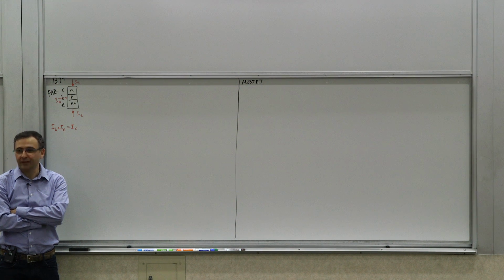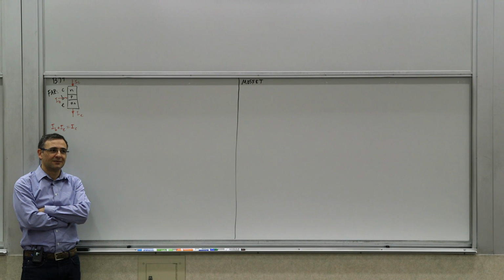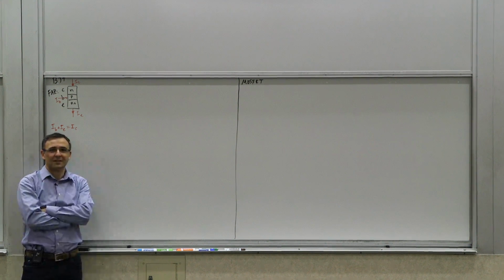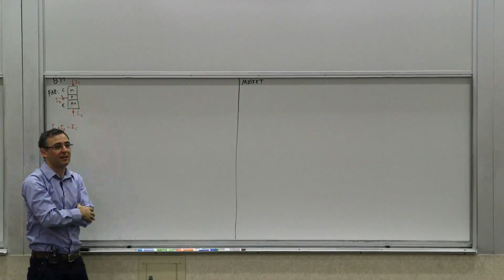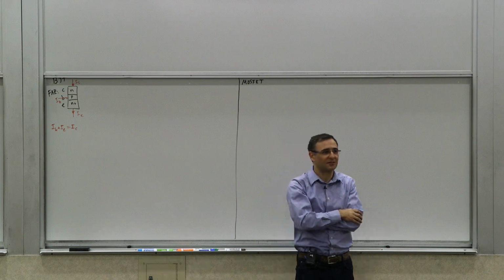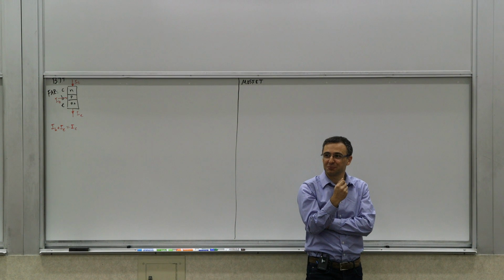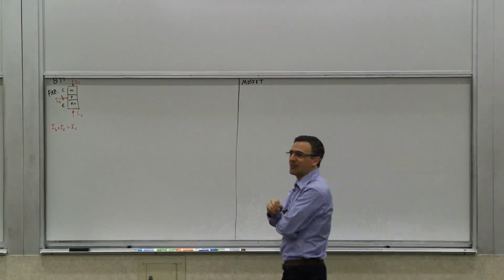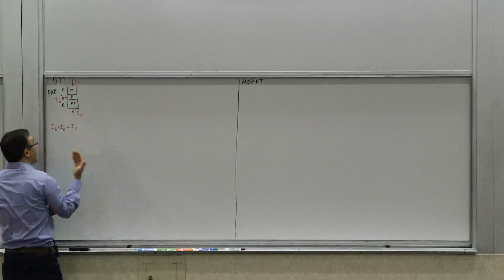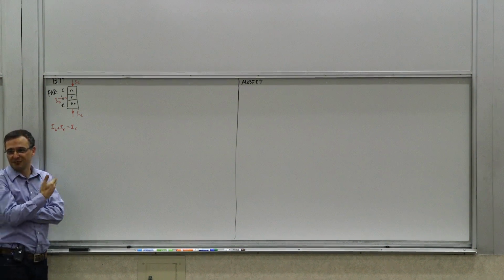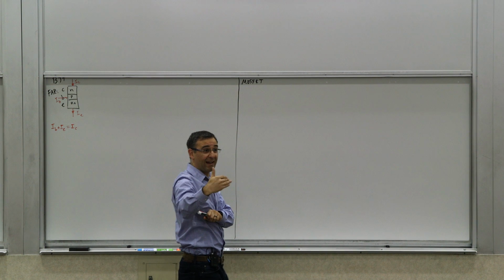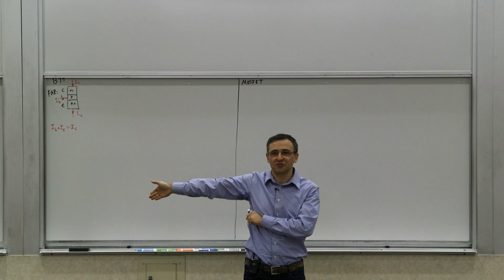For this to fail, KCL has to fail, right? And for KCL to fail, there's a condition that needs to hold. So this should not be a lumped circuit anymore. For this to fail, the dimensions of this device should be comparable to what? The wavelengths of interest, right? These transistors are not really that large, especially if you're talking about integrated transistors, you're talking about microns. So this will fail at optical frequencies for a micron-level or submicron-level transistor. At that point, these transistors are generally not very useful as a transistor, which means that this always holds as far as we are concerned. So the correct answer is that this doesn't always hold, but for everything that we are practically interested in, it does.